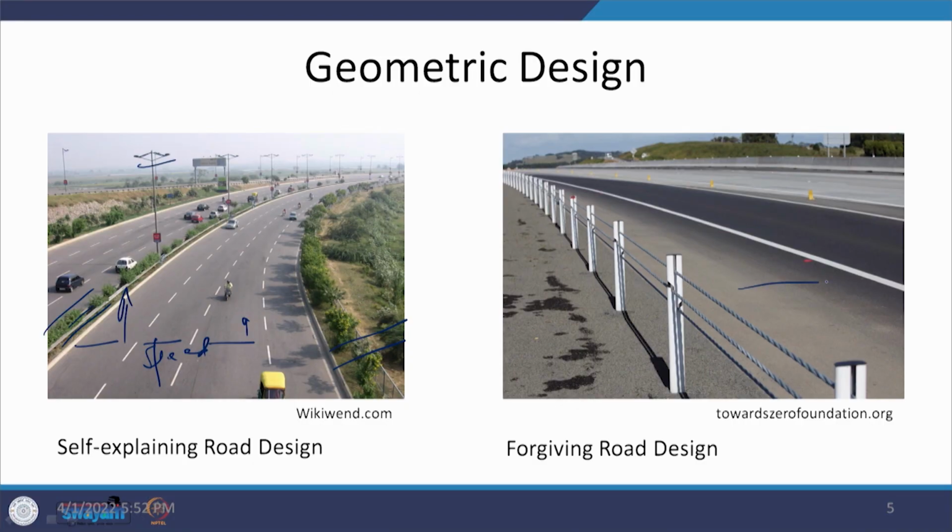On the other design, which you can see, the railings have been provided in terms of steel ropes. If any vehicle hits here, it is going to divert back, and that is what we are intending to provide in this design. At the same time, this is being provided at a certain distance away from the main carriageway, so there can be some space provided at two levels. That means there is a setback at which this facility is provided, and even if the vehicle still goes and hits there, it comes back. So, again, you are providing an opportunity to the driver to rectify the error.